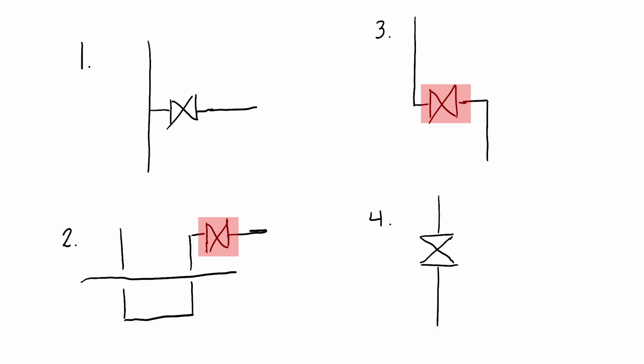Those bends in the pipe there, that's not really depicting anything having to do with the arrangement of the valve in the line and where it can go. It's still going to go in the same direction. Really, it just complicates the drawing. Maybe number 2 is a seal loop, and sometimes you want to depict those seal loops as there's an elevation drop. But even in this case, you could have pushed up that whole pipe section above the straight pipe, so that way you're not cutting in the middle of that U shape there.